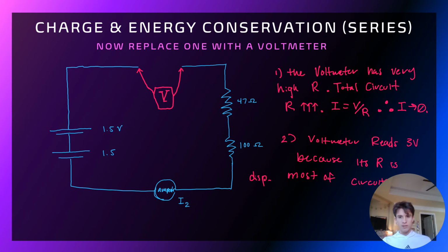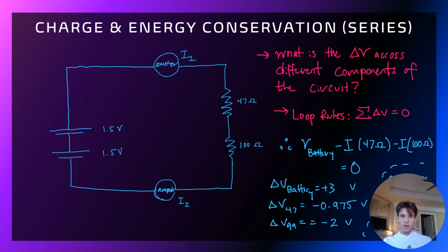And then the question is, why does a voltmeter read 3 volts when you would expect voltage drop to also be coming from these other resistors? And it's basically just the voltmeter's resistance is disproportionately high compared to the rest of the circuit. So 3 volts will drop during that period pretty much. Some sig figs would be off, but...